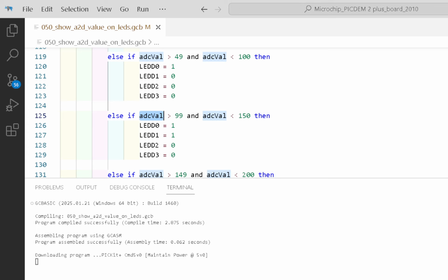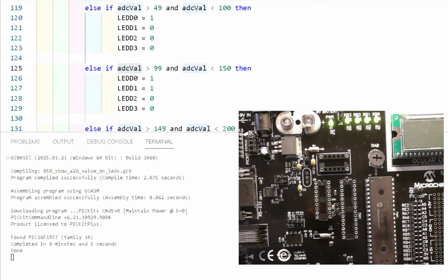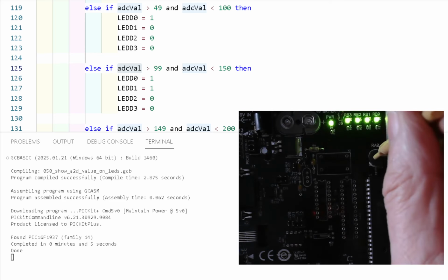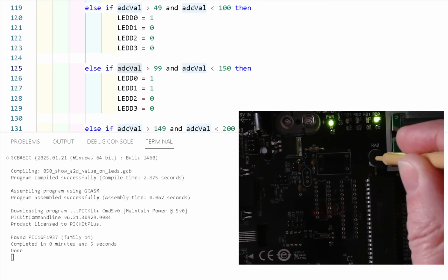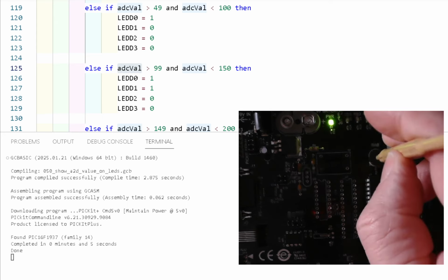It's now popped up the programming window. It's now programming it. If we go out to the desk cam, oh, Zen mode might be better. It's now set all 4 LEDs on. So now time to turn the light off. If I put my tool here, lean back slightly, as I rotate the potentiometer, the LEDs go off. You can see I'm going to rotate that, full on to full off.